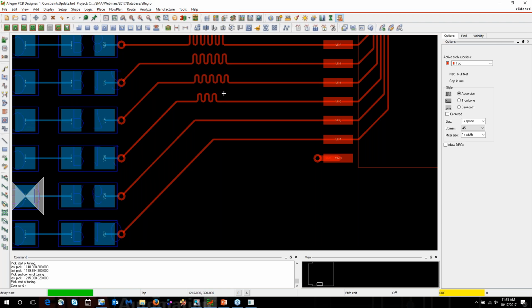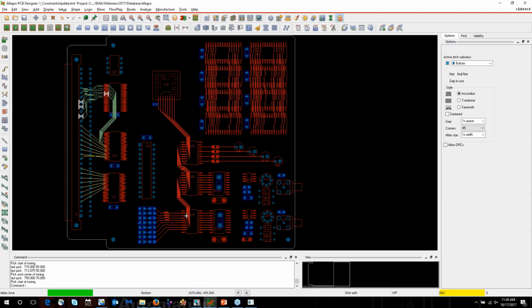And by the way, I could actually add the length over here if I wanted to, because that's part of the same XNet. And we're actually constraining the entire XNet, not just the separate nets. Okay, so this is enough for now. Let's go ahead and save my changes.